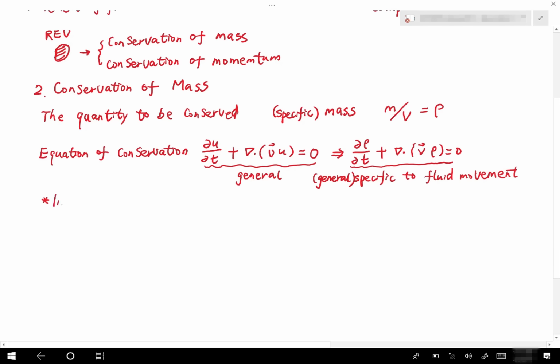That is when the liquid is incompressible, or the flow. So if it's incompressible, then what's going to happen? If this is 0, that means rho partial t is 0, and also this one equals this one, right? So eventually, we can get this equation. So if it's incompressible, we only have a very, very simple equation.